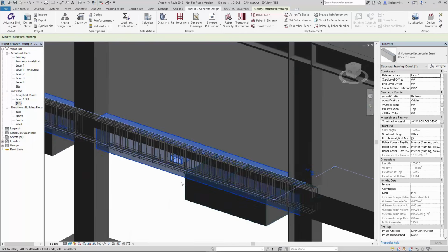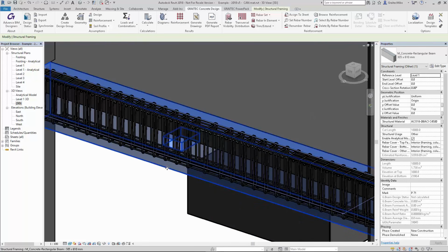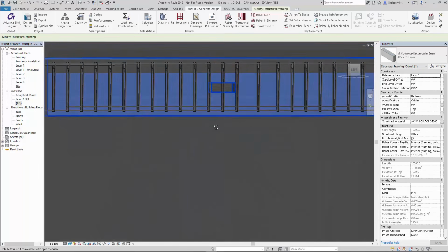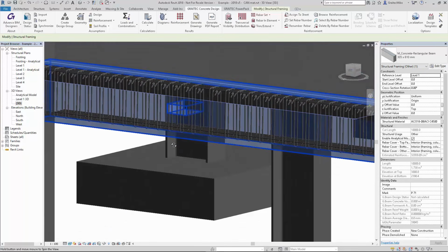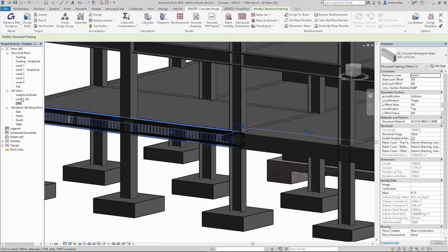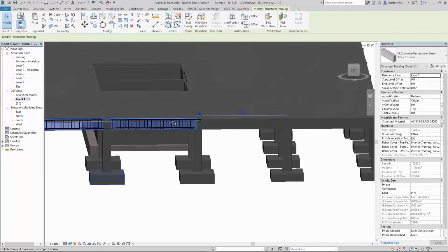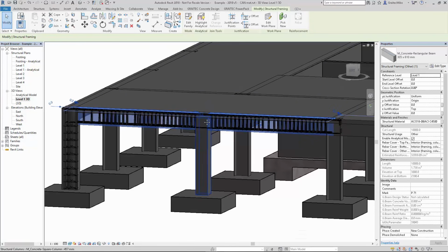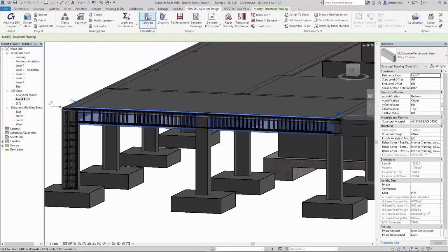What's important to know is that there is still a clash between those rebars. Because we generated the rebar before creating the opening, we're simulating that an MEP or HVAC duct needs to be changed or needs to be added into this section here. So what we would need to do is tell the engineer and have him reevaluate the rebar placement. But what we can do is have this recalculate, and the engineer could validate the calculations from the report created as we had seen previously.